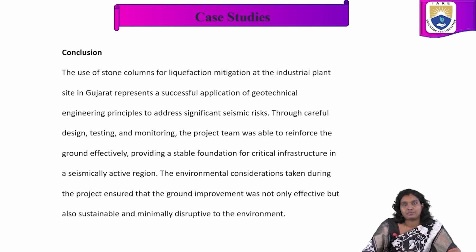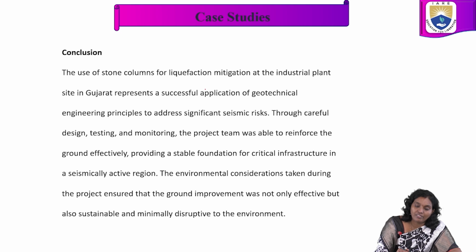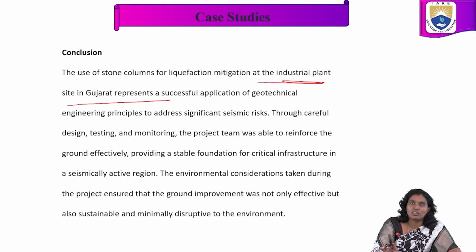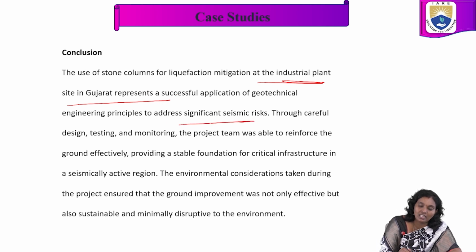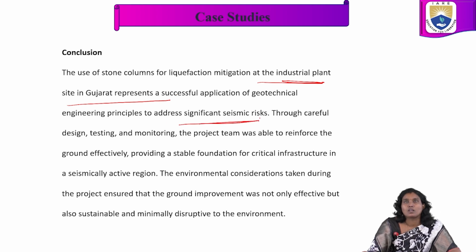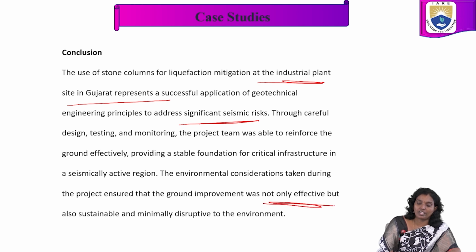Under this particular topic, stone columns for liquefaction mitigation at the industrial plant site in Gujarat represents a successful application of geotechnical engineering principles to address the significant seismic risks. Through careful design, testing and monitoring, the project team was able to reinforce the ground effectively, providing a stable foundation for critical infrastructure in seismically active regions. So the environmental considerations taken during the project ensured that the ground improvement was not only effective, but also sustainable, with minimal disturbance to the environment.